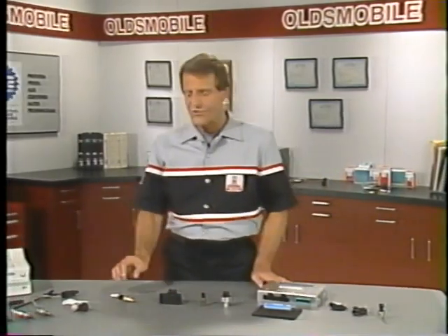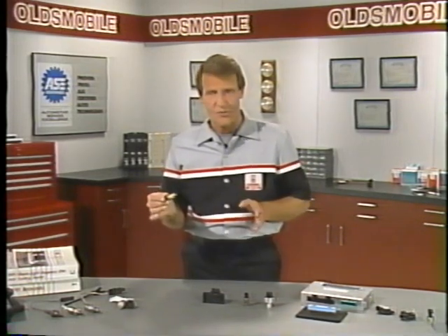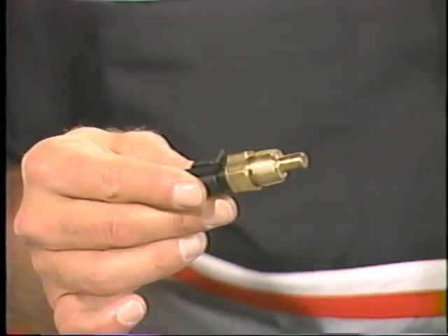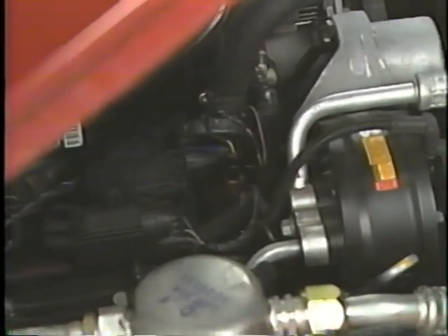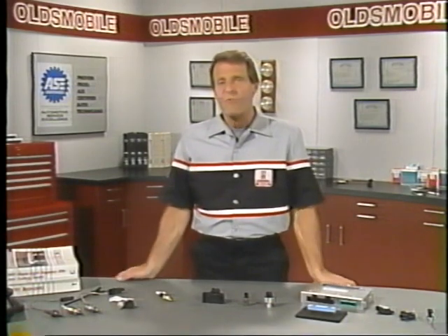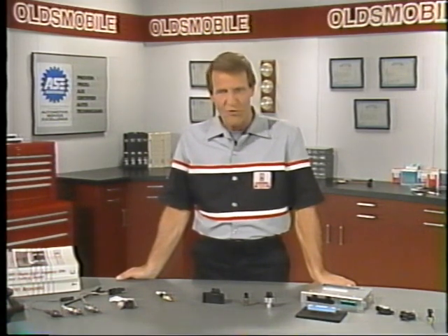The coolant temperature sensor, or CTS, converts temperature into voltage signals. It does that with an electronic device called a thermistor. The sensor body is installed with its probe immersed in engine coolant. As coolant temperature changes, the thermistor responds by changing its electrical resistance. The type of thermistor used in coolant temperature sensors has a negative temperature coefficient.